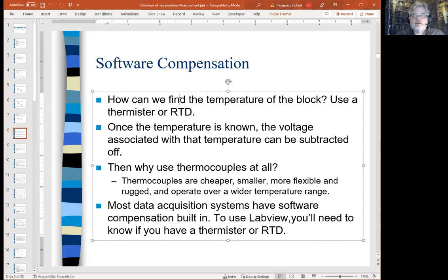That internal adjustment it's making automatically offsets whatever it shows you as your process variable, as your reading of the temperature. So that's really common out there.